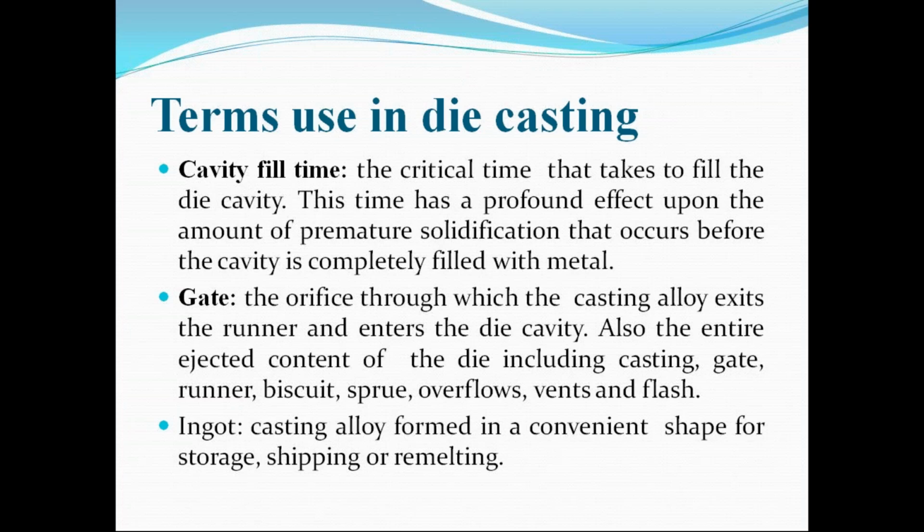If we use a very high time, that means very slow travel of the plunger, what happens? There is a possibility of solidification of the material before complete filling. If we use very little time, that means very high plunger speed, what happens? Turbulence occurs in the liquid material, ultimately affecting the quality of the product. So we cannot choose a very fast time or a slow time. Here it is required to choose the optimum time, which is called the critical time.